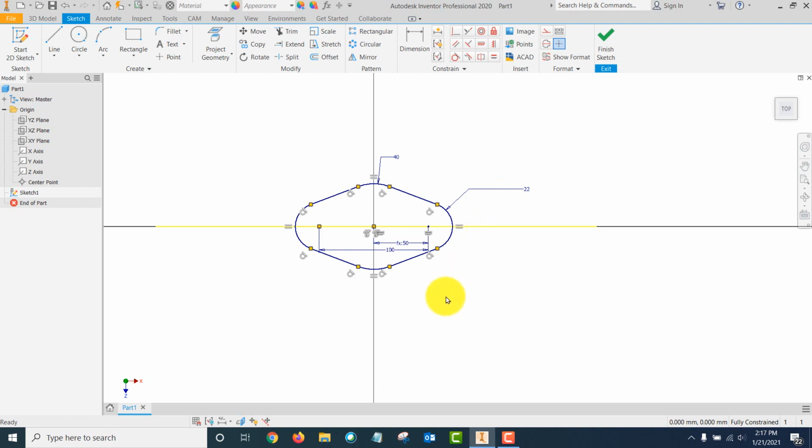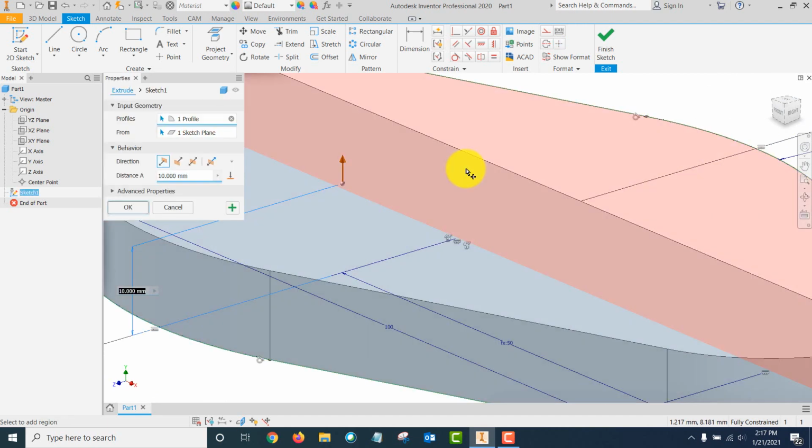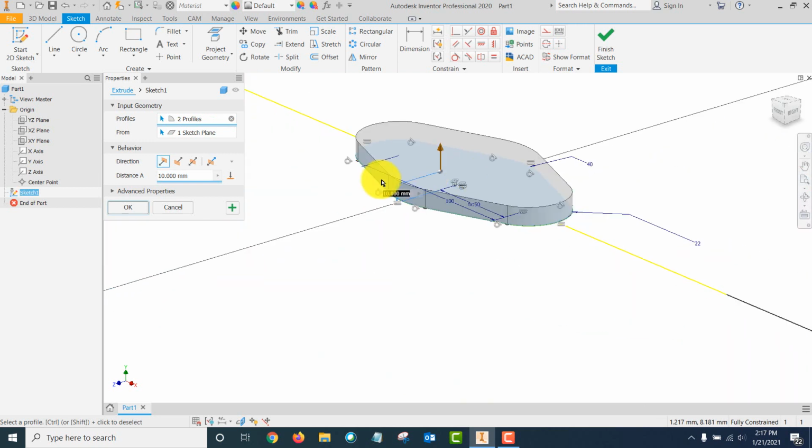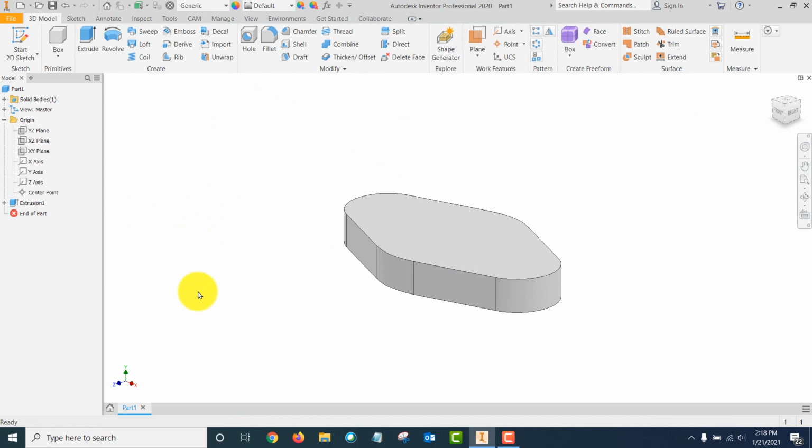I've got all my dimensions in. It says I'm fully constrained, and you can see all of the constraints there. I've made things equal, left to right, top to bottom. Everything is tangent, and I've got the dimensions, so we're good. Now we can extrude this to a thickness of 18. Pick both faces, extrude it up, 18. All right, that looks pretty good.